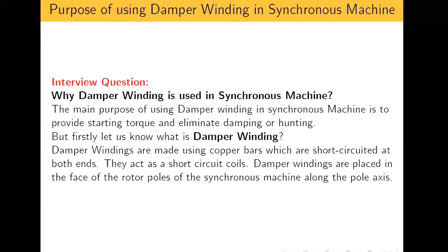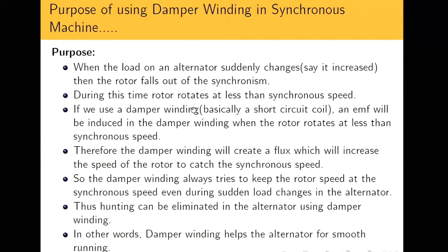What is the main purpose of damper winding? They provide starting torque and eliminate damping or hunting. Though I have given the purpose in terms of points, you can write it as a paragraph in your exam. In a presentation or a PPT, it's better always to show it in terms of points. We will have only two or three purposes for damper winding, but I wanted to discuss point wise what is happening, which is why I have placed this slide here.